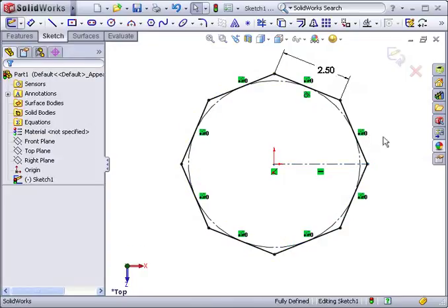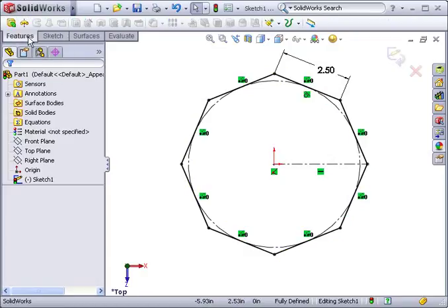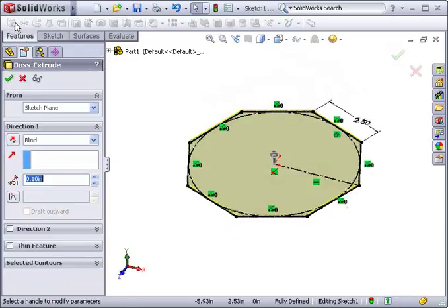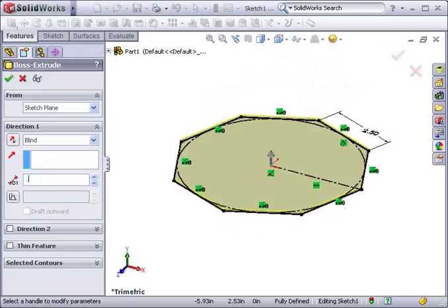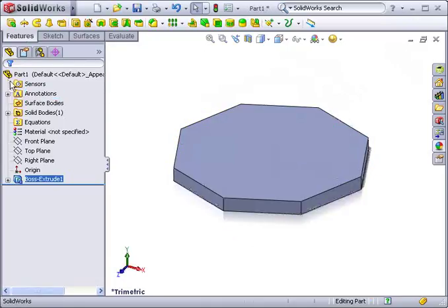With the polygon defined, you can go on to extrude it, or whatever you need. I'll extrude the polygon to give it some thickness. Now, because the polygon has a construction circle already created within the sketch, that's all we really need to create the concentric mate. However, creating an axis is another really useful approach for adding the references needed for mating.